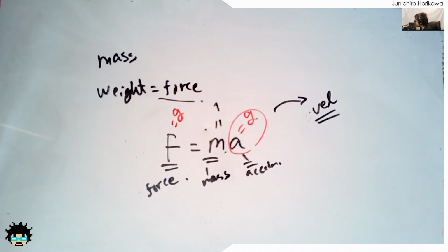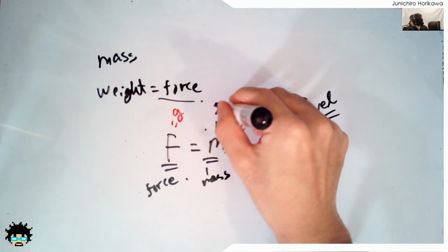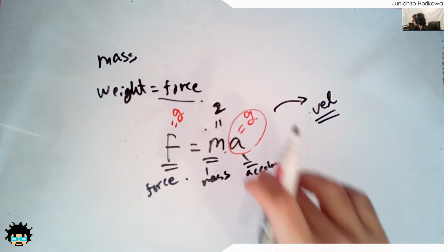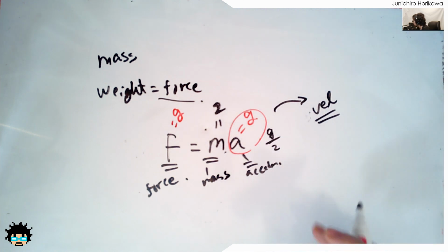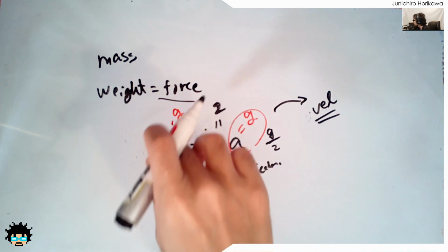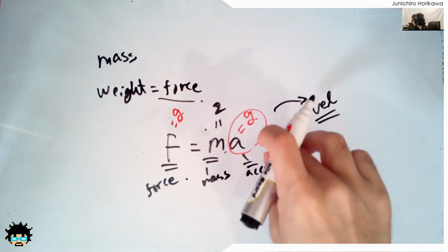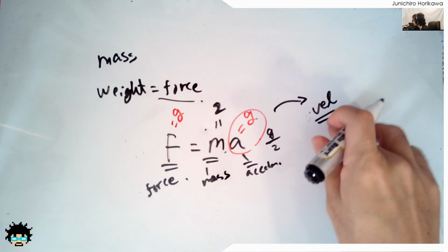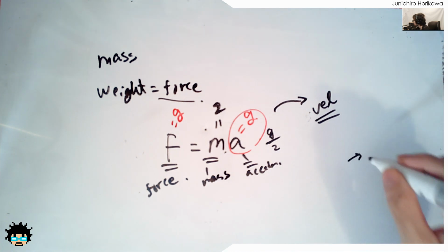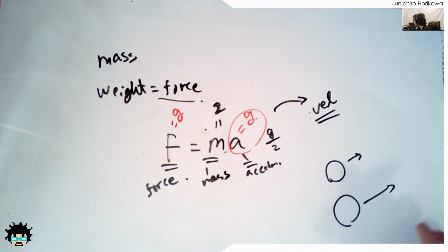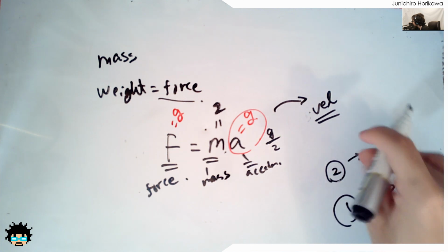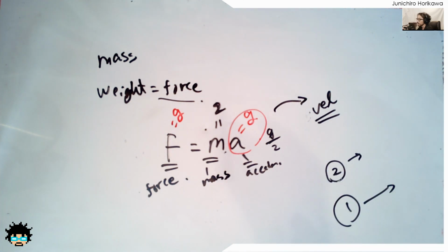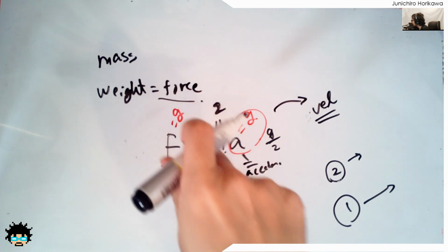So what if I change the m value to 2 then? In this case, the a value becomes g over 2, like this. So it becomes half the size of the original gravity force. And we're going to use this half-size gravity added to the velocity, and as a result the movement becomes slower. Previously it was going at this speed, but by making the mass bigger for this second object, the actual speed which is going to be applied as velocity becomes slower. So this is how it works with the mass property.